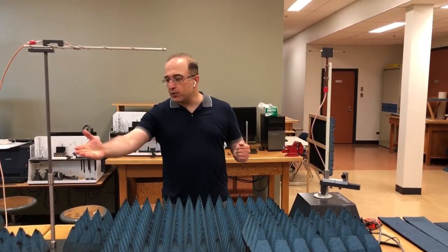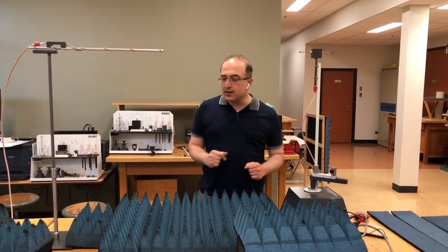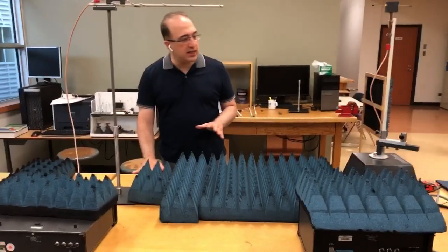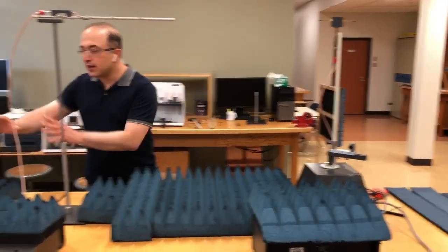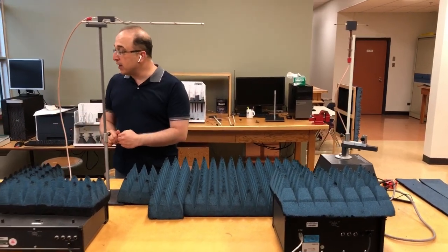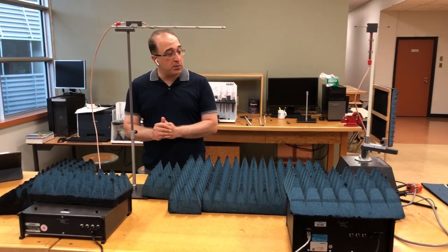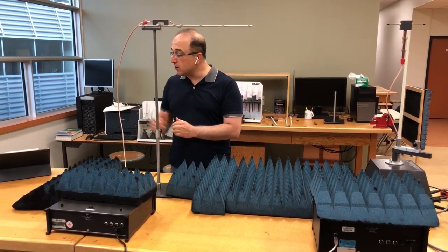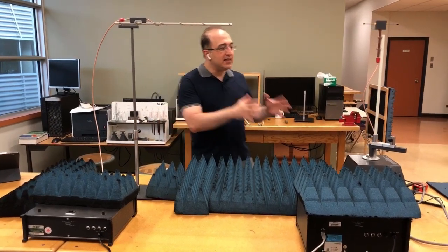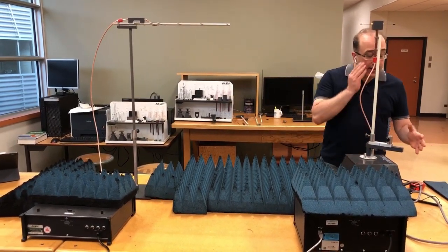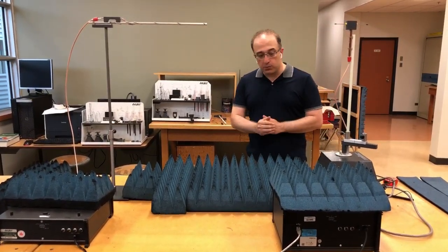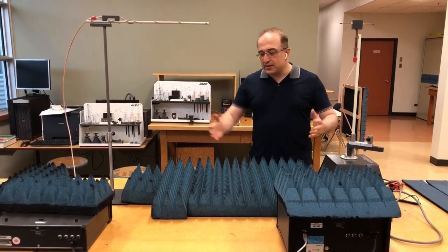Now, I could, for example, make this a little bit farther or make this a little bit farther. But if you notice here, we have two tables. If I move the transmit antenna to this side, probably I'm going to place it on a different table, and I could have some problems with vibration on the other table because I will be sitting there. So it's better for mechanical stability that I move the receive antenna a little bit farther. In that case, they're going to be both on the same table, and hopefully the table would be stable during the measurement. So this is one measurement.